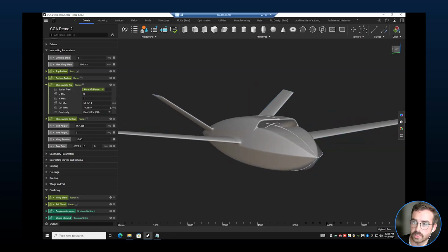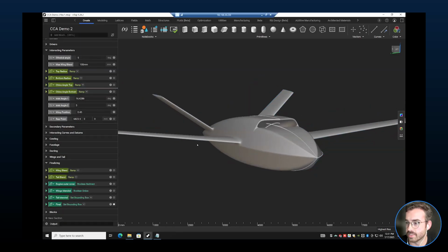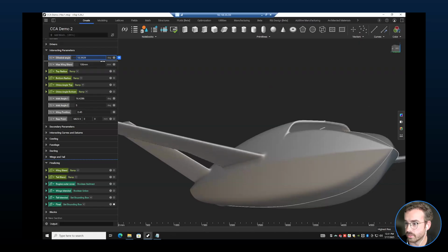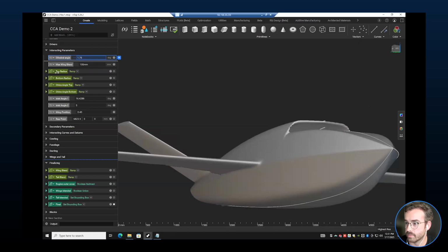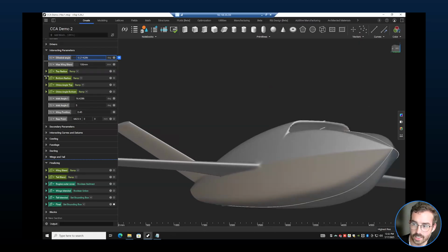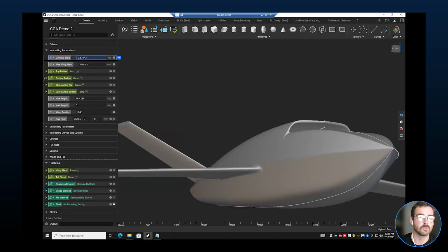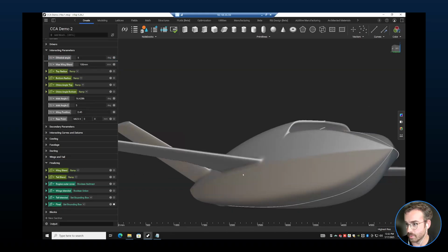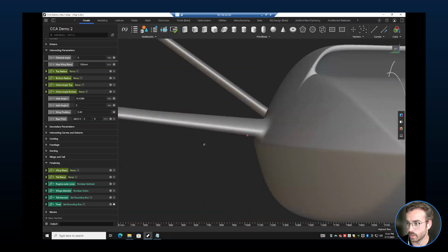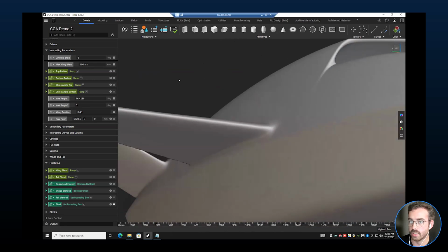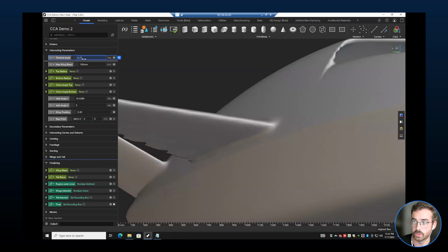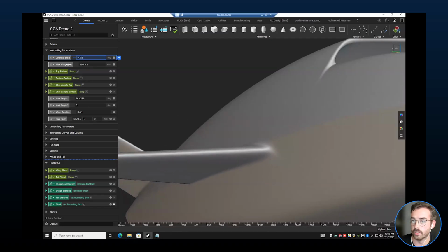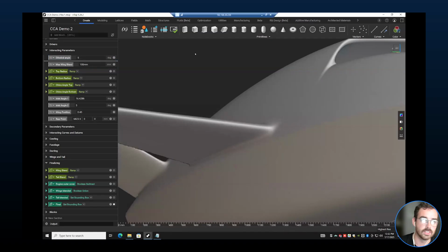So we take that one, that's implicit. We can do other things. This is kind of a fan favorite, is the dihedral, like Adam was showing. So if I move that one upward, move it down, you can see this is like, if somebody has never seen implicits before, this kind of tends to freak them out because, right, if I zoom in here, we've got this blend and it's going over this hard edge. And it's not like a visual trick or anything. This is real geometry. It's actually computing everything. And there's no risk of having a surface that isn't watertight.